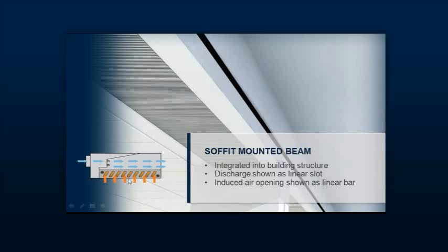So one common problem you might run into in an exposed space like that is if the air doesn't have a surface to flow along, it might start migrating downward toward the occupants. And the worst thing you can do is hit an occupant in the head. They'll notice that air volume around their body, unless the velocity is lower than around 50 feet per minute.